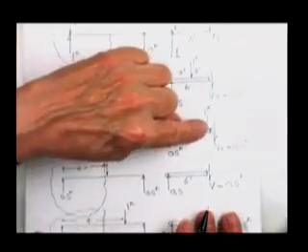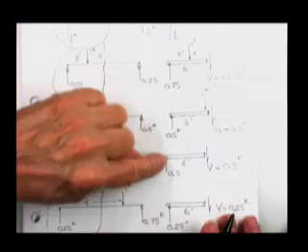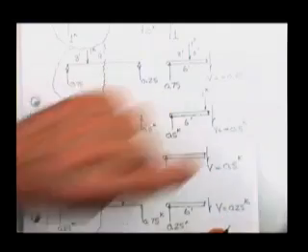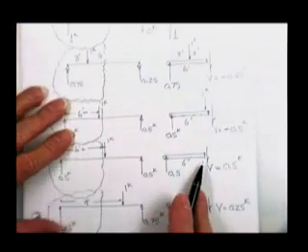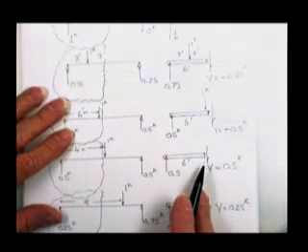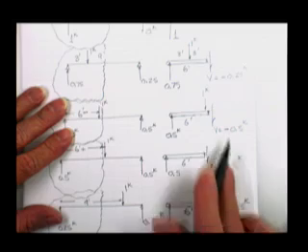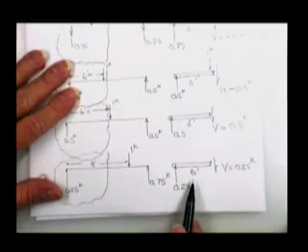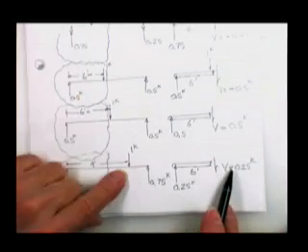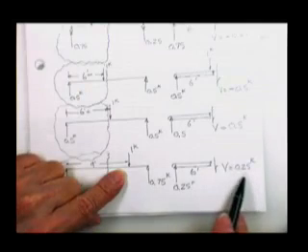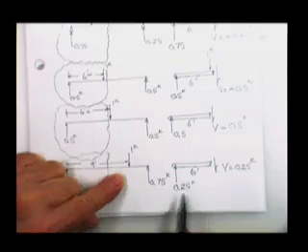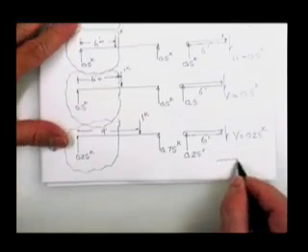When it's moved to the 6-foot mark, minus 0.5. When it's moved across the cut point, the point we're looking for the influence line, it changed signs, and when it went out to the 9-foot mark, it got to be 0.25.